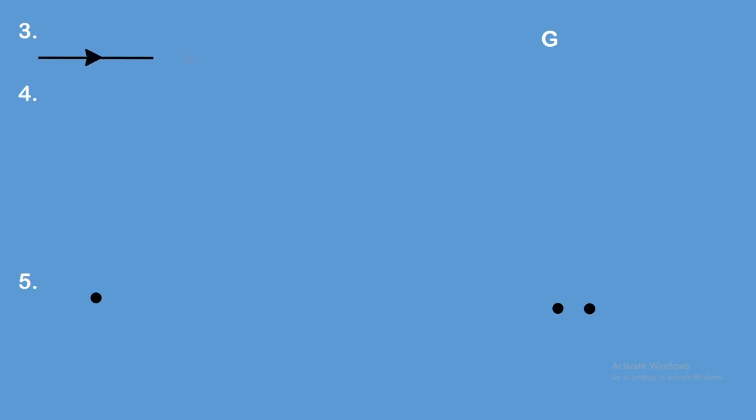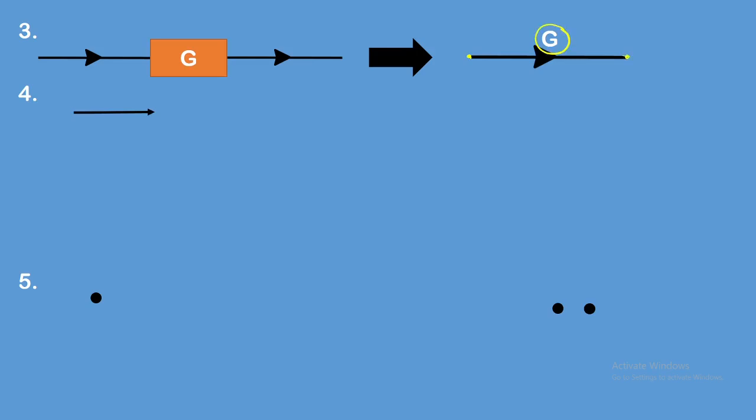Let us take another example. Whenever you have a gain in a box like this, you can represent it simply with a branch traveling from this point to this point, with the gain. That is point number 4 that we already discussed: with the gain, with the arrow mark you have to indicate between the two nodes. The nodes we assume are variables, from input to output like this.